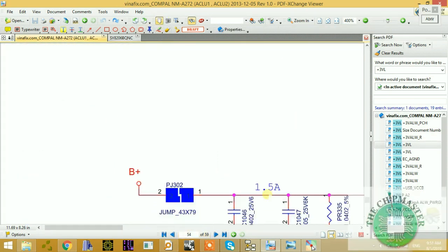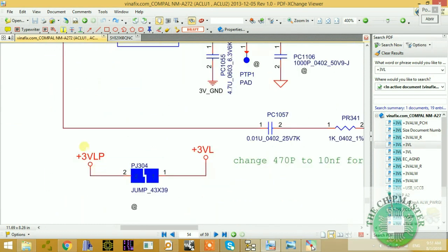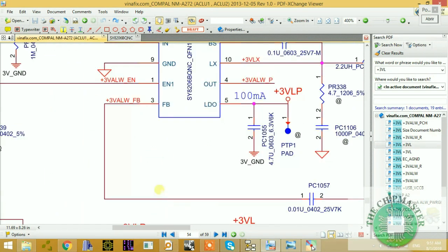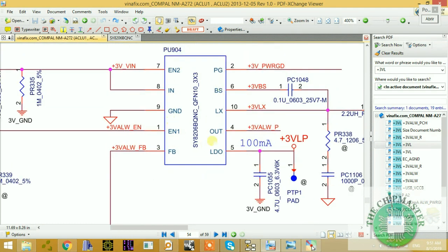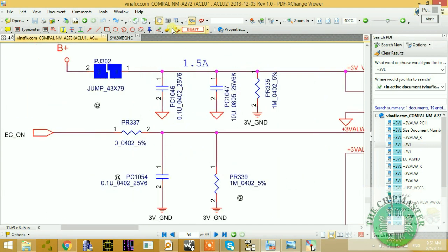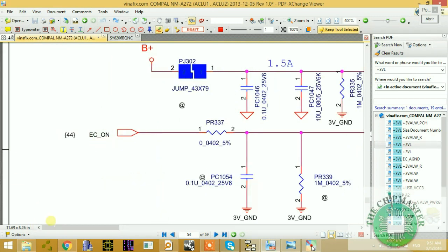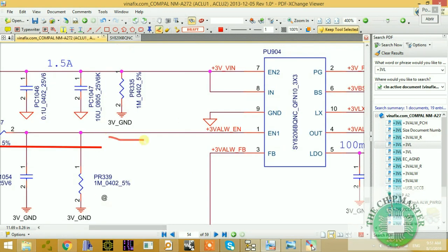Yes. Alright, so enable is out and it's powering the IO controller. What's the next working condition? Anybody can tell me what's the next working condition of this chip? Now we have supply, we have an LDO output. Next we need enable. So the enable is coming from who? Who's sending this signal? This signal is coming from the IO controller, EC, as I said before, and it's coming to pin number 1.